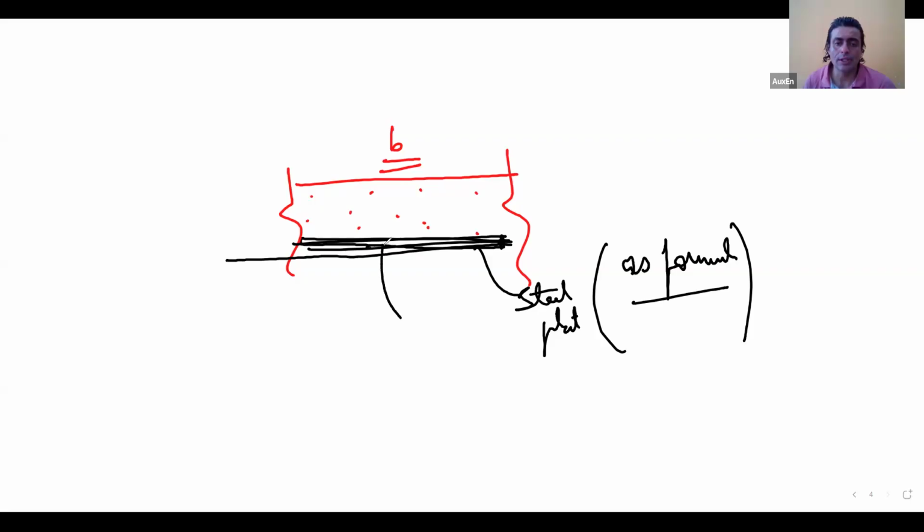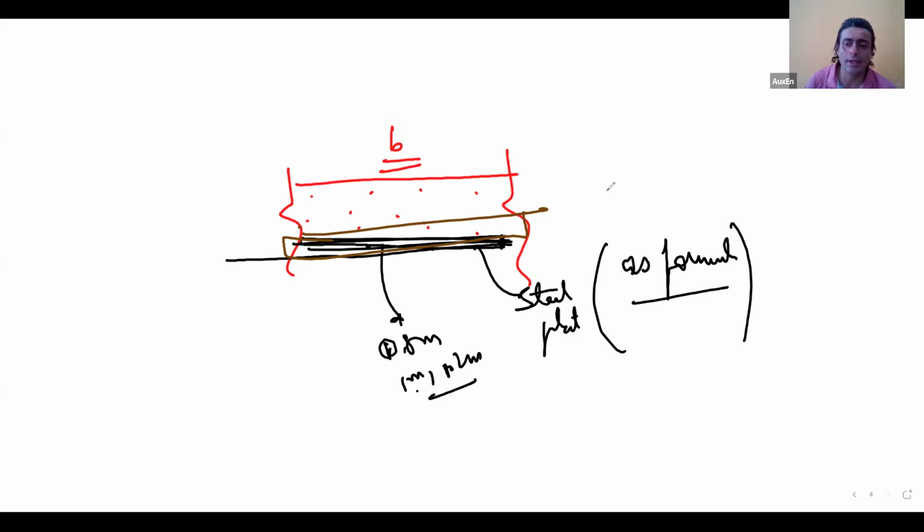The steel plate in itself is so thin. I'm using, let's say, 0.8 mm or 1 mm or 1.2 mm or 2 mm. That's it. The steel plate is very small. I cannot have such a small, thin steel plate being used. If I want to go beyond, let's say I want to use a 6 or 7 mm thickness plate, then it does not become cost effective. Then putting a scaffolding and putting a reinforcement is much cheaper than putting a 6 mm steel plate as a formwork and reinforcement. You get my point?